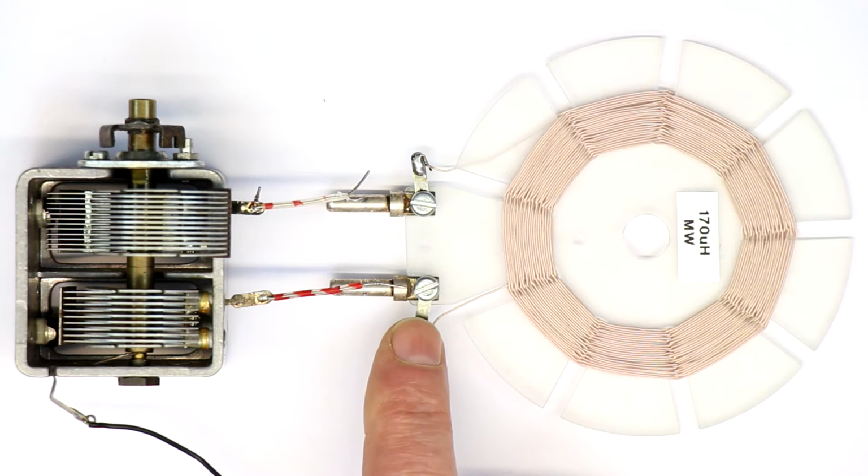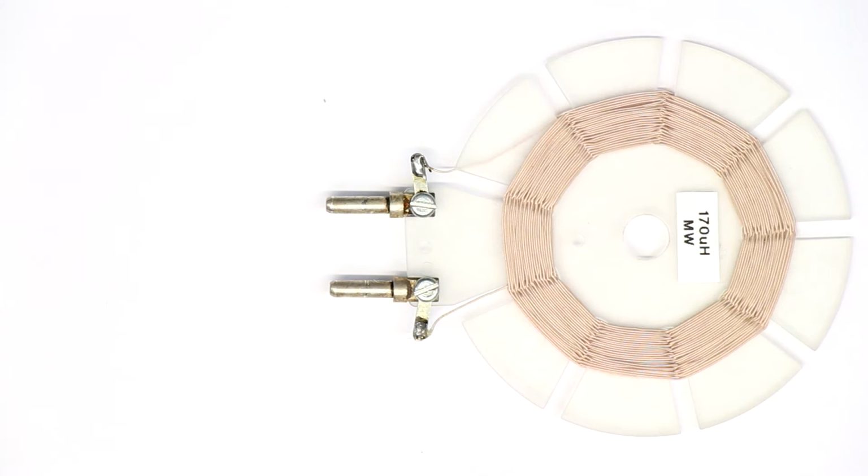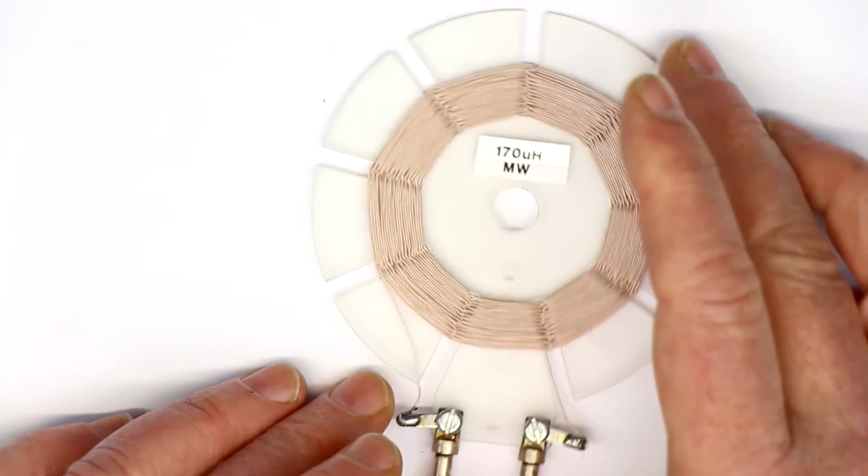The calculated or simulated Q factor was 500, and the measured one is only slightly above 100 at a frequency of 1 megahertz. So we already had the conclusion there must be other detrimental effects that ruin your Q factor except for the DC ohmic resistance. And now let's take away the variable capacitor.